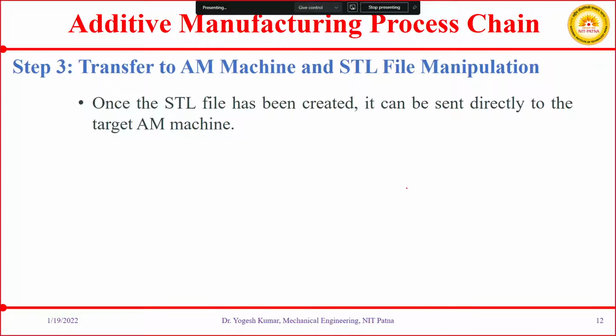So once you have got your STL file, you will transfer this STL file to an additive manufacturing machine. Nowadays it is standardized. Otherwise, in the past we had to transfer it to slicer software, where you can create layers of the part.